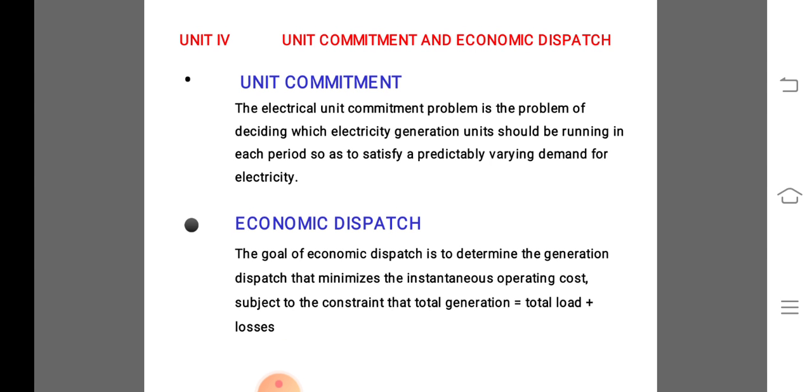The operation economics can again be subdivided into two parts. The problem of economic dispatch deals with determining the power output of each plant to meet the specified load such that the overall fuel cost is minimized. The problem of optimal power flow deals with minimum loss delivery, wherein the power flow is optimized to minimize losses in the system. In this chapter we consider the problem of economic dispatch.